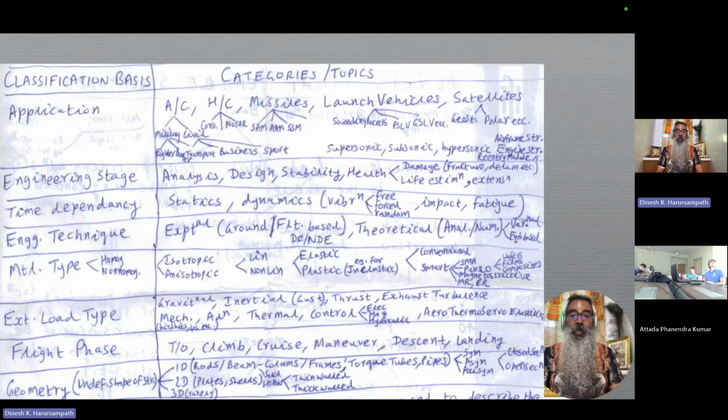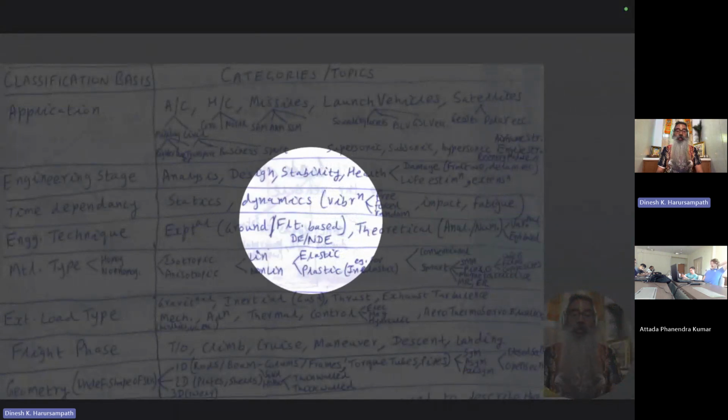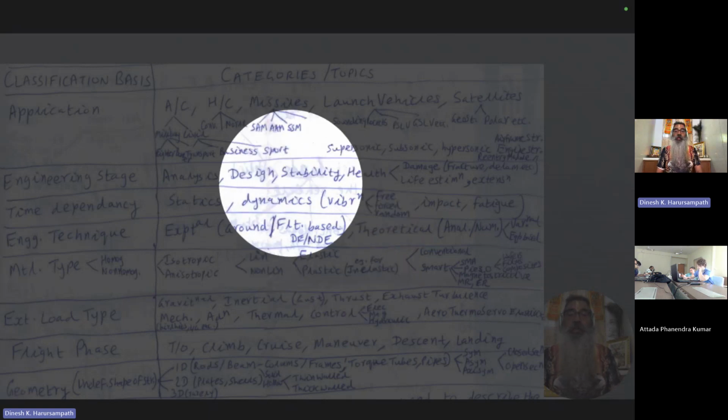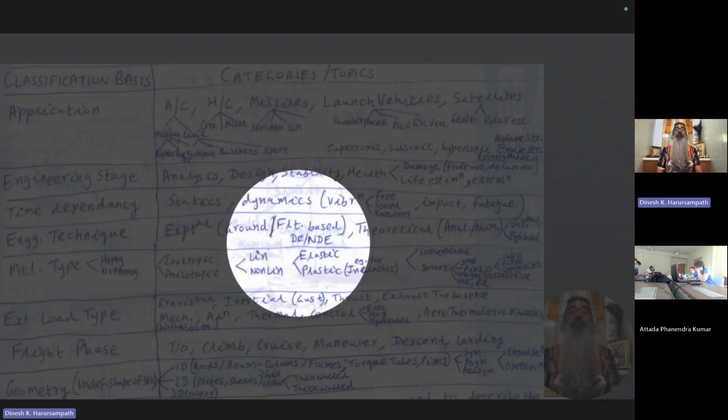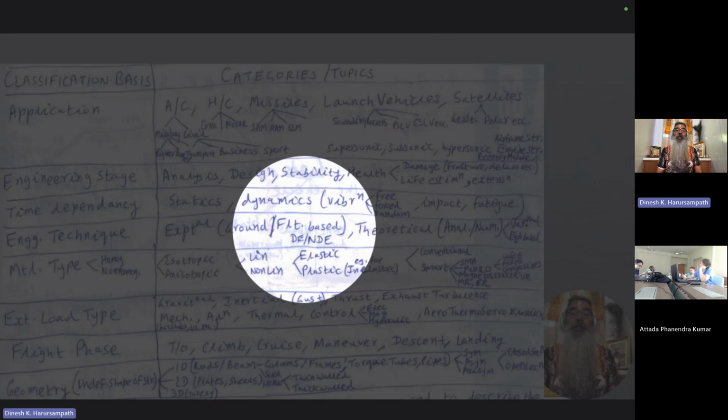Yeah, so that's as far as the experiments are concerned. Destructive and non-destructive evaluations, of course, have many different ways of doing it, like X-rays, ultrasonics, thermography, radiography, various other kinds of things that are used, which do not destroy the structure, but still get a lot of useful information. And this has become a very critical part of a lot of aerospace structural analysis and design as well.